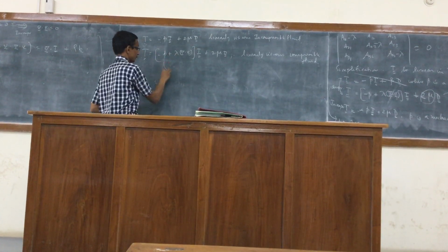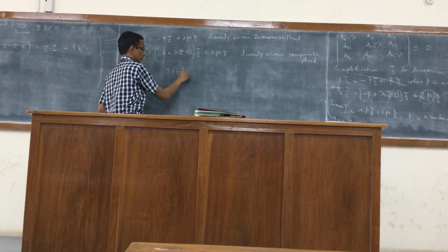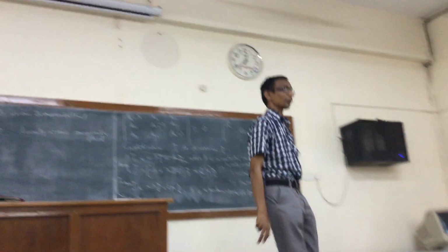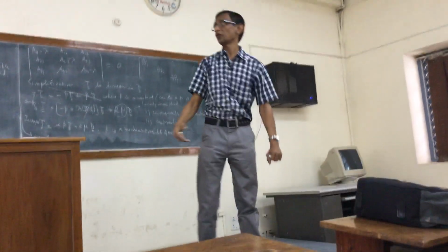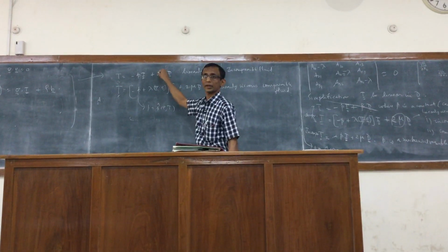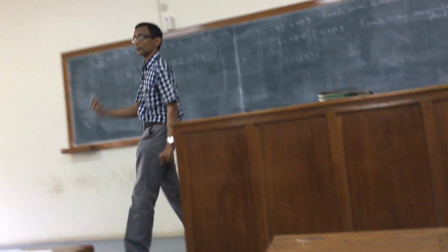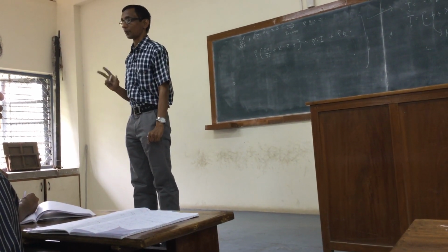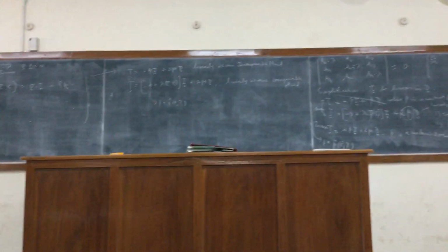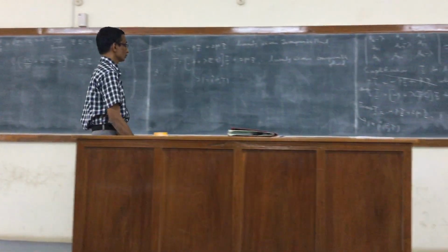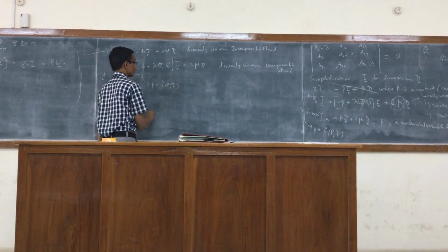Importantly, I should also write here that rho is equal to a function as given by the equation of state. That's a very important thing you have to keep in mind. Because on the face of it, if I put del dot v equal to 0, that is the divergence, I get this. Right? But there's another distinction between the compressible and the incompressible fluid, and the way you approach solving the equations will be somewhat different, because the pressure has to be solved for in the case of an incompressible fluid. So pressure is a function of density and temperature. Yeah, but T and T is confusing a little. Oh, okay. Yeah, temperature.